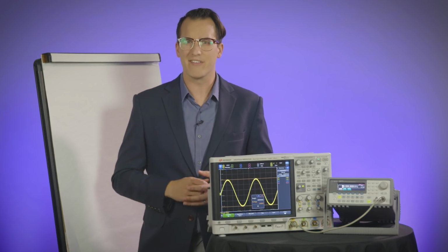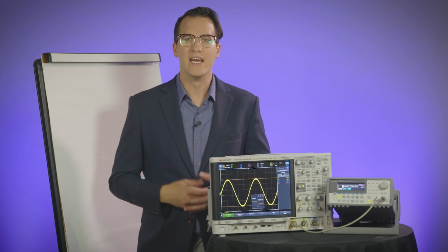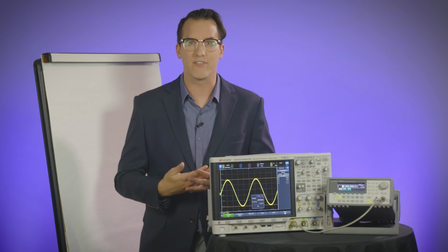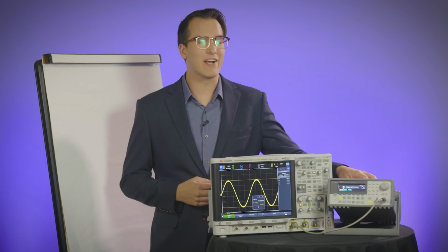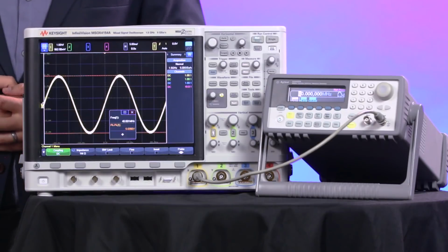But this signal is going to be attenuated by 3 dB or so because in Test Gear 201, you hear that the signal will actually roll off a bit near the maximum bandwidth of your system. In fact, you can actually see frequencies that exceed the bandwidth of your scope. For example, here's a 40 MHz 5-volt peak-to-peak sine wave piped into my 1.5 GHz oscilloscope.